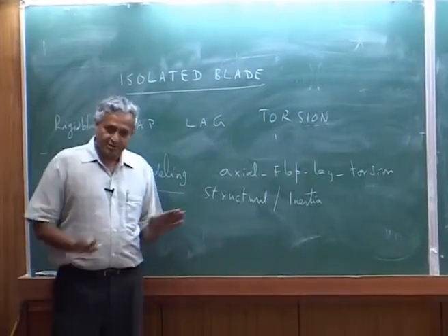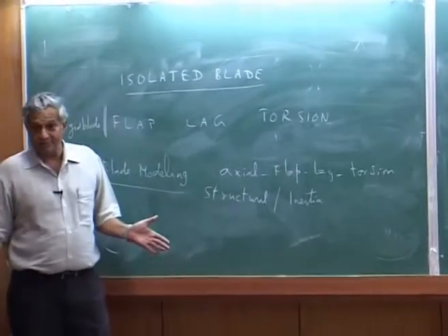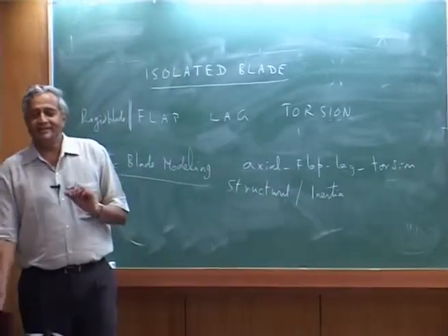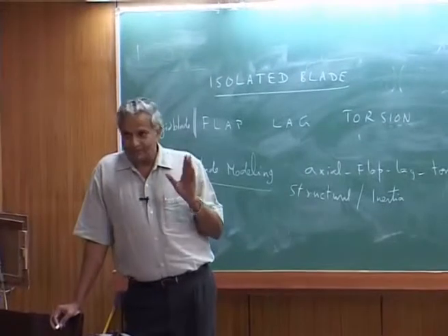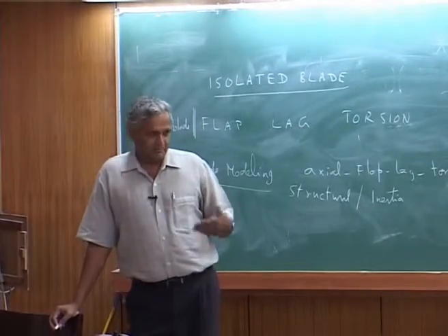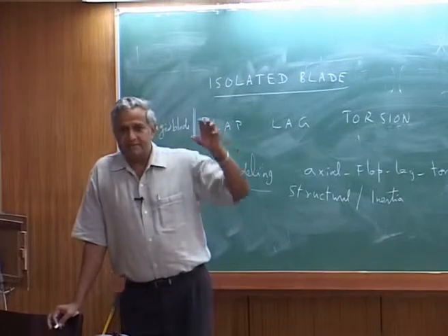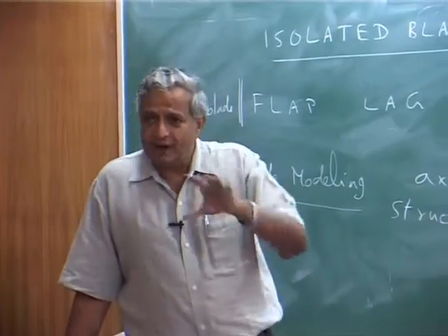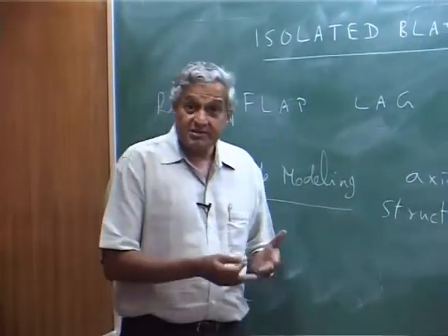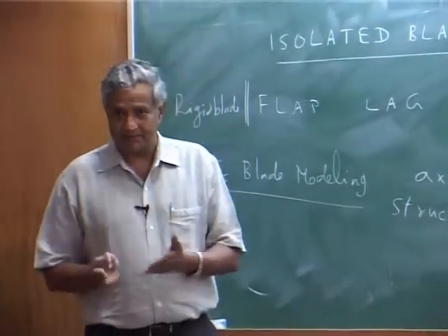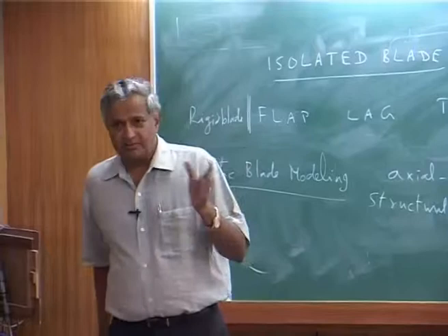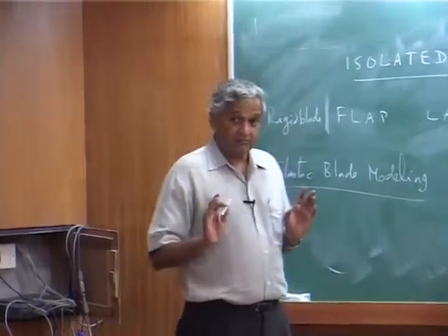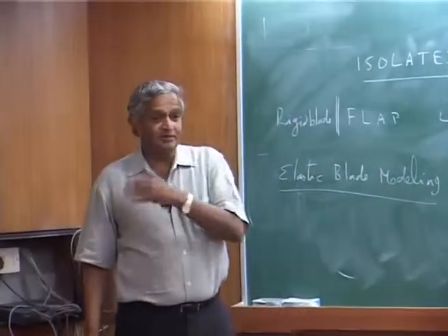Another one: aerodynamic modeling is required if you want to solve the aeroelastic problem. Traditionally, people use a relatively simplified aerodynamic model, simplified in the sense of quasi-steady with dynamic stall, with some dynamic wake, etc. All, because that's what we have used. Now today CFD is entering into that. People have worked on the CFD problem and are trying to relate it, but it's some approximation. Still, it is not fully advanced to the level that you can do everything.